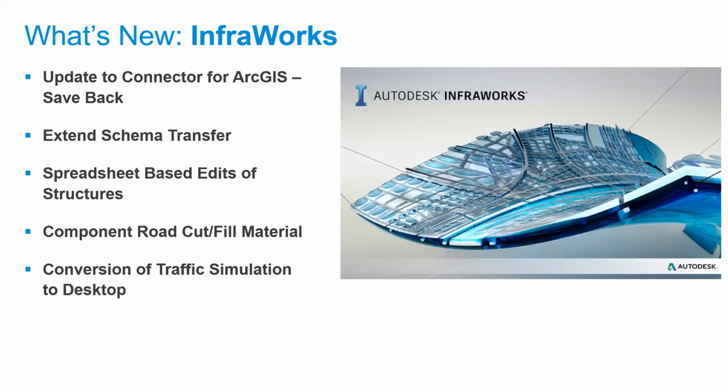There is also the update on the component road cut and fill material, where you can now change the specific color for your cut and fill, to differentiate between the areas along that particular road corridor that you are cutting and the areas that you are filling.